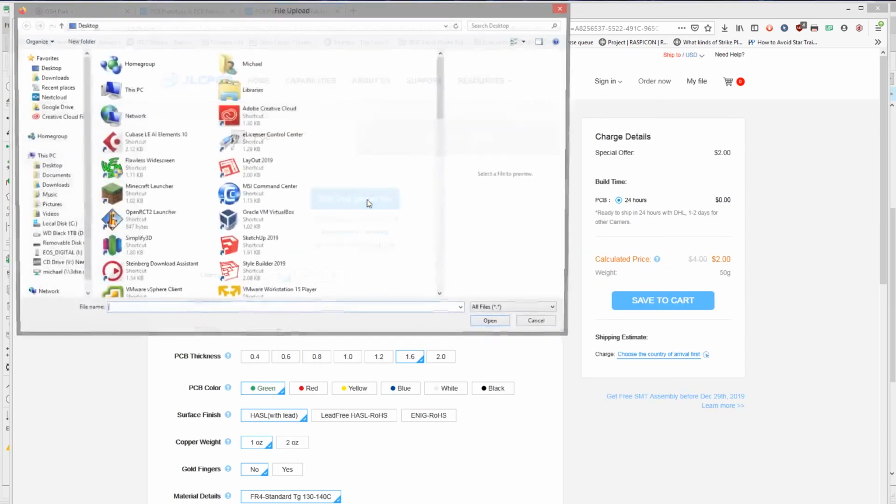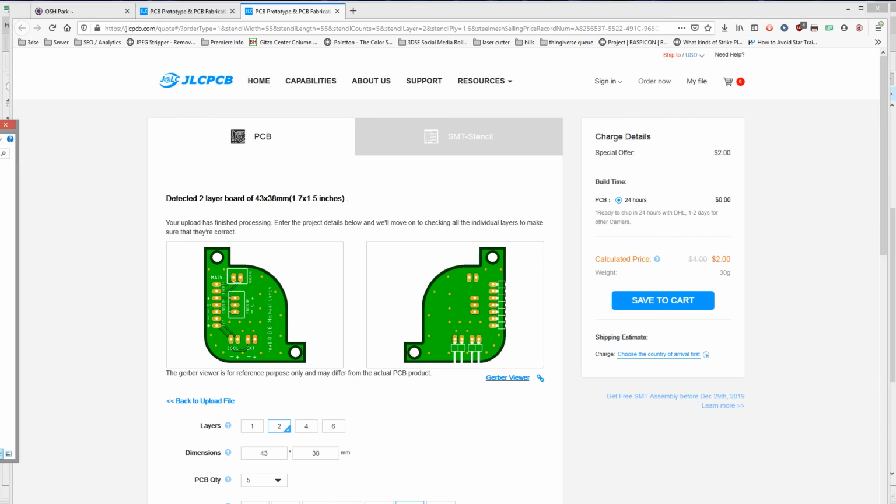And then we're going to look for our Gerber file. One thing I would recommend is saving your projects into some sort of cloud-based or backed up directory, because by default, I think it'll just save your Gerber or all of your Eagle files and projects to the documents folder. If you don't have that set up for Google Drive or whatever service you use, like Nextcloud is what I use, if you're trying to sync between multiple PCs, or if you need to back it up, it won't automatically be backed up. So just something I recommend personally.